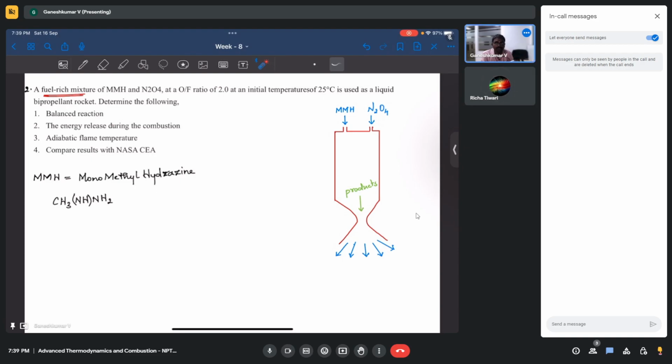So you are converting it into thermal energy. But in a rocket, what we are interested in is the force. We require force to propel the rocket into space, right? If you want force, you need to convert that thermal energy into kinetic energy. That's why a lot of gases have to be pushed out with a higher velocity from the rocket. When you see a rocket launch, you have a lot of gases coming out of the rocket.